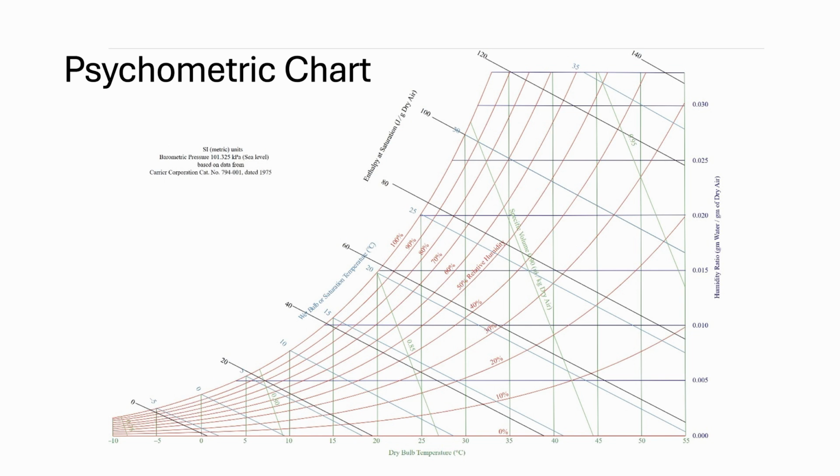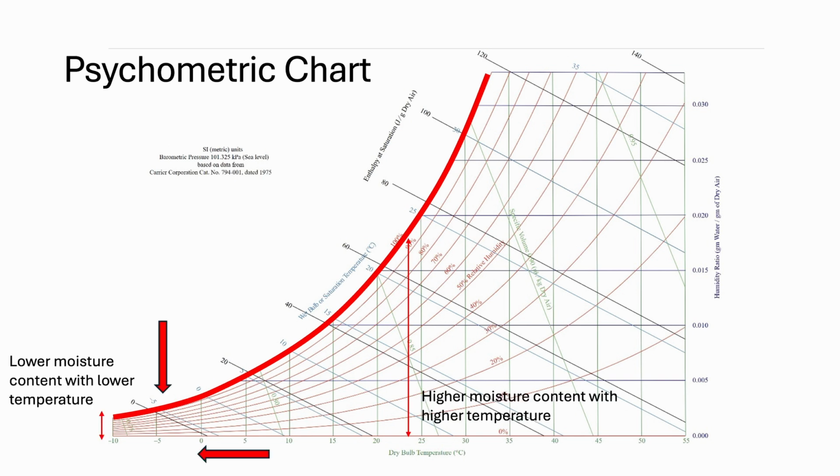contained in the air. As you can see in this graph, depending on the temperature, you may see different levels of relative humidity. In other words, if we see the top line, this is the condensation line, so it's the line where the relative humidity is 100%. This means that if there is moisture and the air is in this state, it will condensate. It's 100% humidity, it's water. As you can see, this line is not constant depending on the temperature, but it decreases with temperature of the air. This means that the colder is my air, the lower is the amount of moisture that the air can contain, because the easier is to condensate.